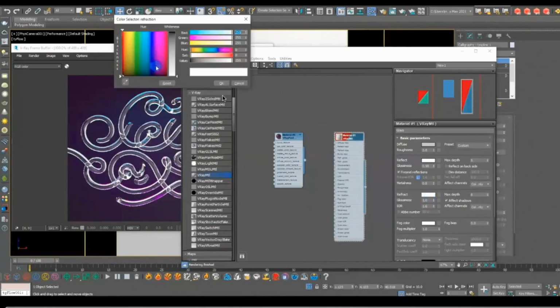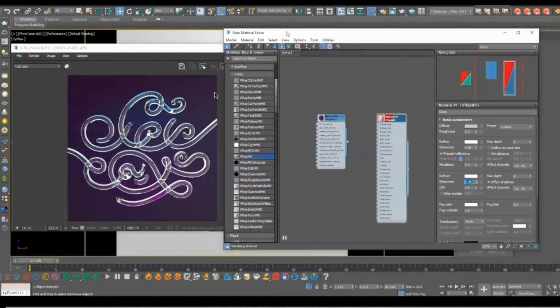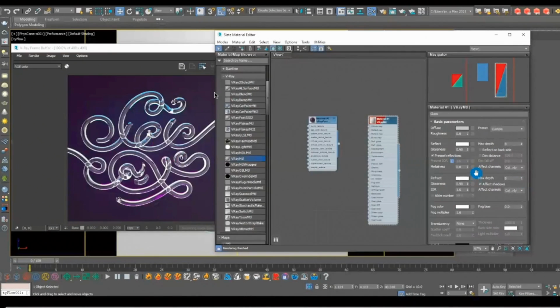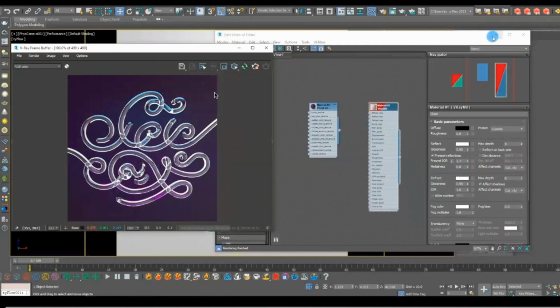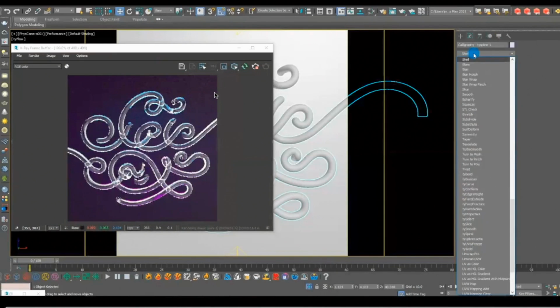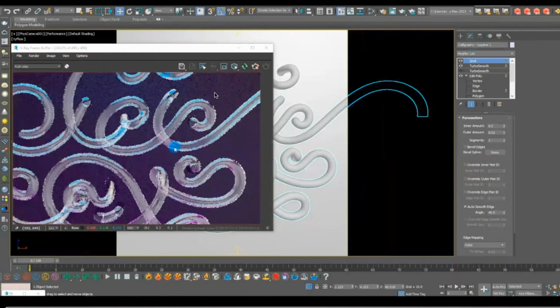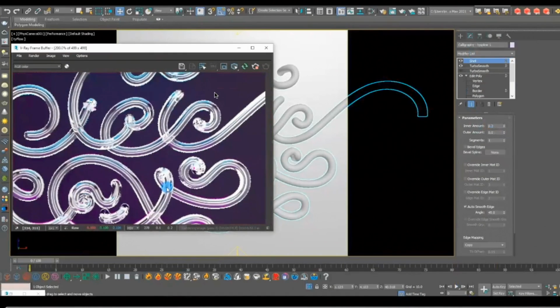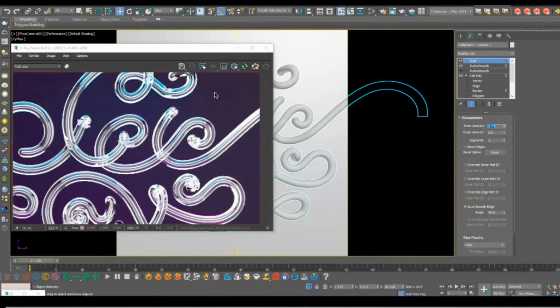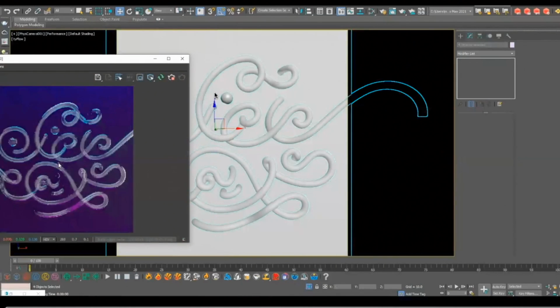And then the next step in this part is setting up your glass tube. Because we have the lighting set up, even if it's 100% see-through, a glass material, and 100% reflection, you can see the HDRI starting to play its effect on the glass tubes. And that's basically it for this point. Super easy setup. Just to recap, it's an HDRI map, some fill lights, and setting your calligraphy piece to a glass material. That's basically it. That's beautiful.